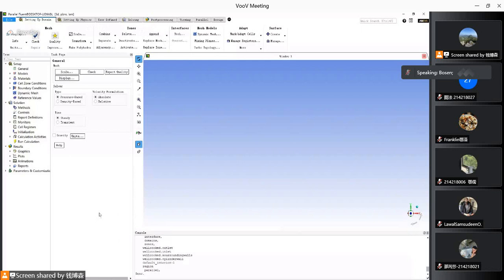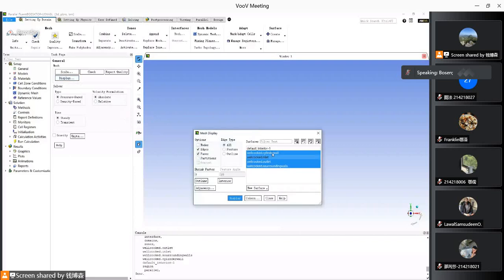Okay, we've done the import in the ANSYS Fluent section. So here is also a two-type of window, but I will show you later. First of all, a lot of beginners for ANSYS Fluent will begin wondering, I have done the import, where the hell is my model? So to show your model, first of all, you need to click on display, and select the features you would like to display, and then click on display in here.